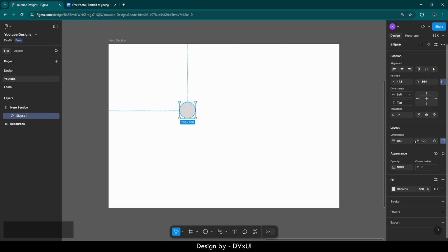Well, by clipping it, they have joined together, and if I change this value, which is the height, to 2190, the width will also change. So this is the benefit of clipping. If I unclip it and change the height to 100, the width will remain the same, but the height will be changed. So this is something that we don't want. So let's go back. So the height and width is going to be 2190.